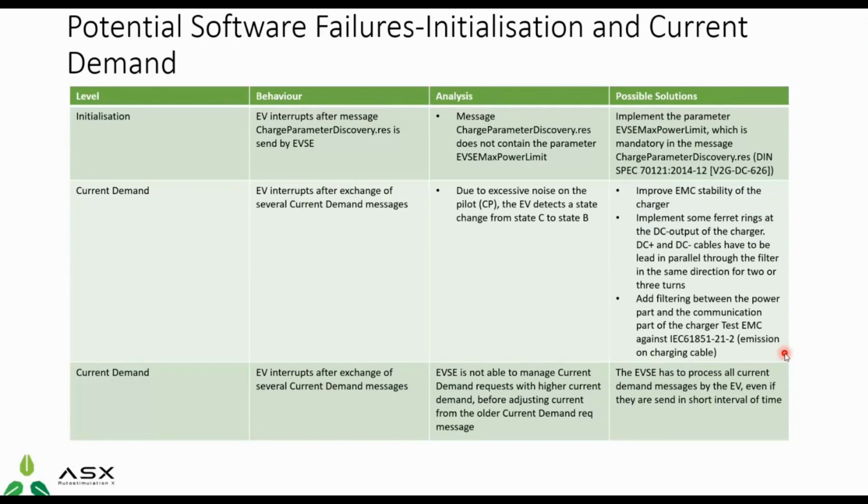It may be because of excessive noise on the CP side. Many times we have seen the chargers failing because of EMC stability. So for that simulation, we have to improve the stability of the charger, and to improve that stability, you must know what is going on and why it is interrupting. The simulator gives us the result of why the charging process is stopping.